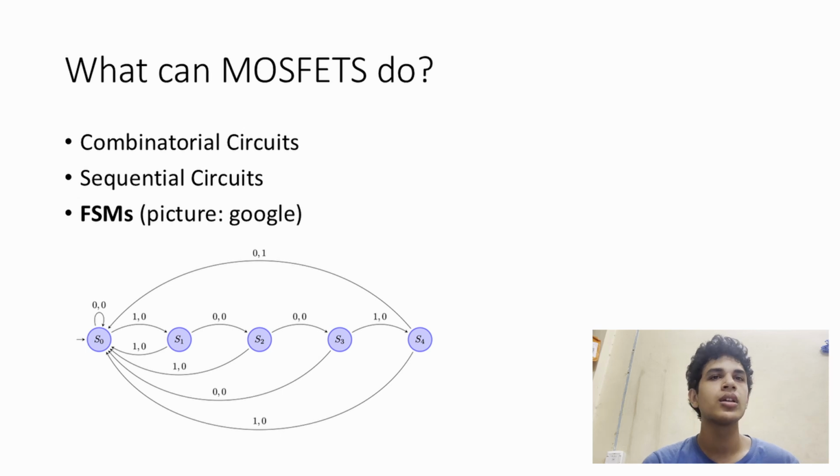So a small recap of what we have learned from electrical engineering, and also to some extent what would have been the progress, I assume, in the 1960s, is you realize that digital circuits can be used to implement combinatorial circuits that are only a function of the current input, and clocked sequential circuits that are a function of the current state of the registers and a function of the inputs to the system at that time. And combinatorial circuits also have a logic to update the states. So essentially, based on what the current inputs are and what the current state is, it can be used to update the states. Basically what we realize is combinatorial circuits and sequential circuits can be used to implement FSMs.